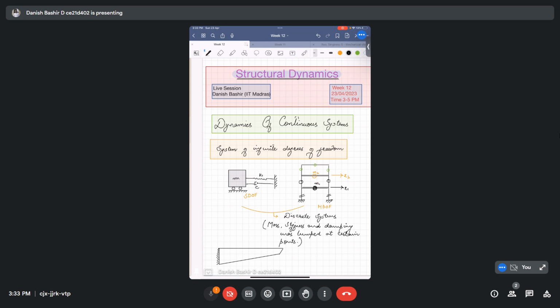So we are having A1 cross section here, A2 cross section here, and we are having different distributions of the reinforcement inside the beam, and different densities inside it. We are having rho 1 here, rho 2 here, totally random, so we cannot use the concept of lumping the mass at a single point. If I take one point here, it has a tendency to show motion w(x,t), w1, and this point will again vibrate, w2(x,t).